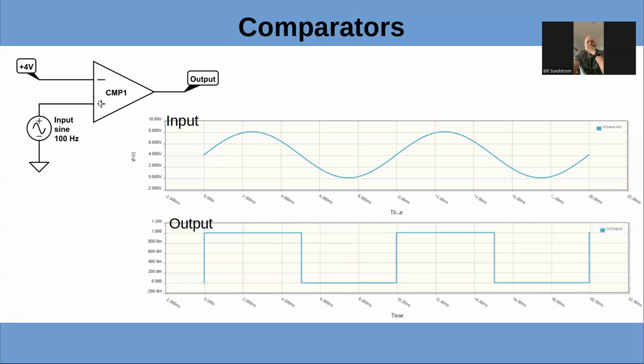So when you add the hysteresis, depending on how much it is, let's say for an example, it was 1 volt. This wouldn't go back to 0 until the input got below 3 volts. So you'd have 1 volt of noise immunity. It would switch high until it got to 5 volts, if you do the hysteresis balanced.